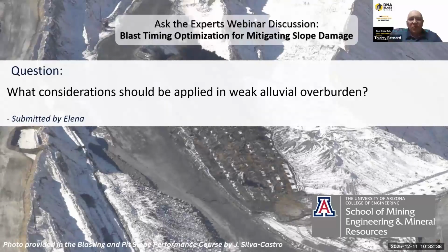Yes, James, I would like to add that if you have decided to blast, it could be useful to have a drill with measurement while drilling on board and use this information to know exactly the hardness of the rock, the weakness of the rock, plus or minus, and to use the correct explosive depending on the hardness of the rock that you measure.